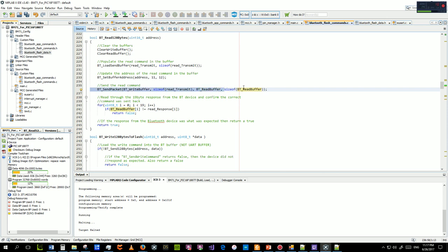Now, the size that we're sending is very, very important. I want to point something out here. If the response from the unit is supposed to be like 147 bytes, which in this particular case it would be, which is the full size of the read buffer, so I expect once we send this command that the BM71 is going to give a response that's 147 bytes.